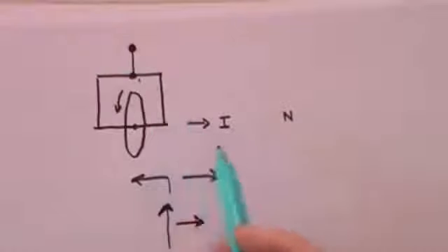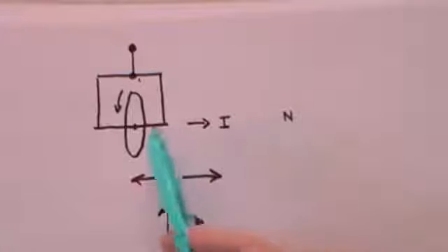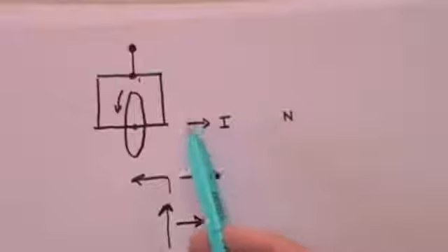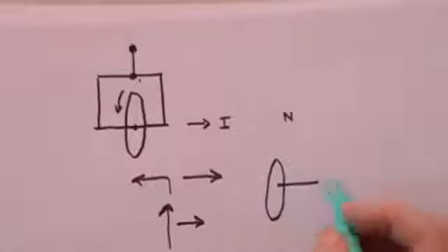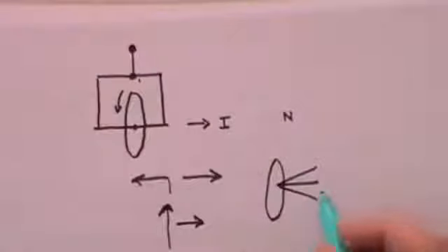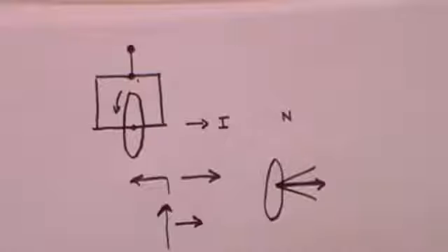Not only will it continue to point in this direction, but of course it will also continue to point in the same direction if we're looking at it sideways on. It won't change like that or that either. It will always keep in this direction. So it's not only telling you the correct latitude angle, but also the correct longitude angle. And this is why it's so useful for navigation purposes. If you have a spinning gyroscope, of course you need to make sure it keeps spinning, then it will always point in the same direction no matter how much the object on which you're travelling may be twisting and turning.